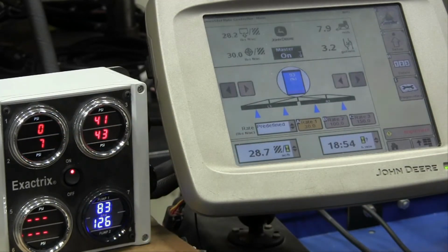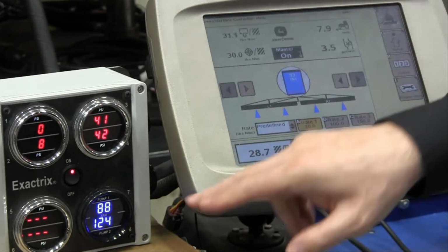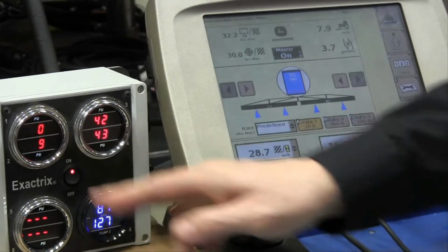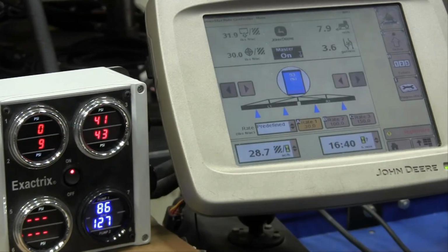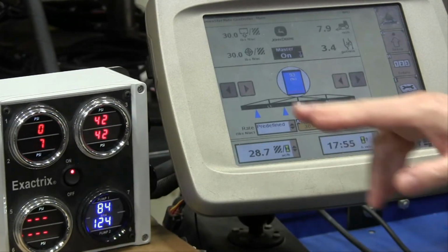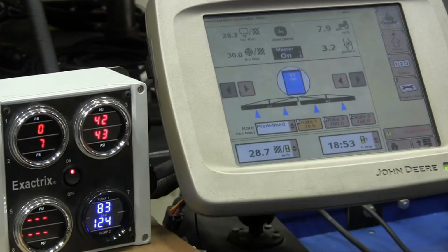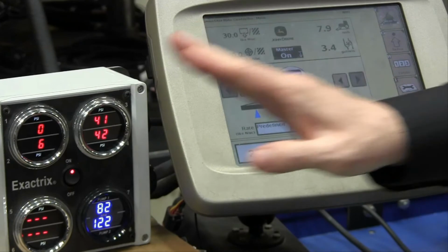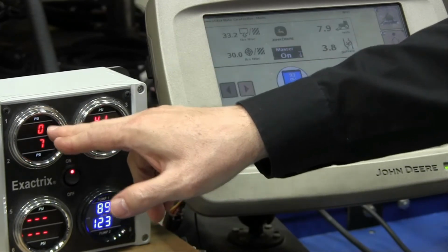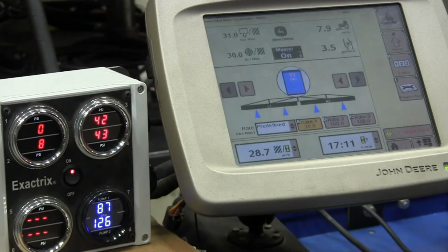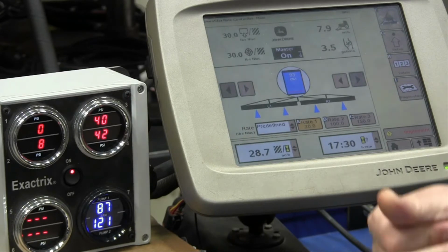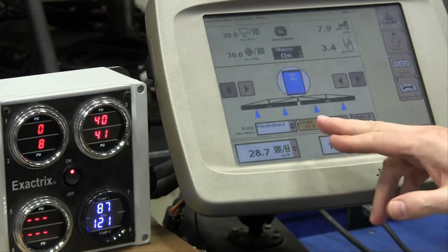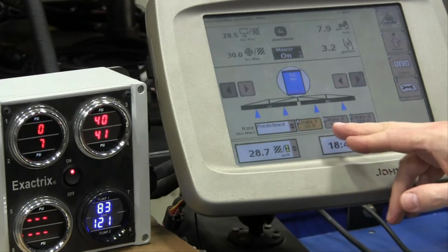And James, I'll tell you when I think we're hitting the target on the money. Not necessarily by this number, but when the pressure comes up, then we know we hit the target. So the pressure tells the story at the injection point. This gauge right here, even though it's reading 0 right now, has virtually no flow going past it. When that pressure comes up, wham, you got it. So let's go from 30 pounds to 150.